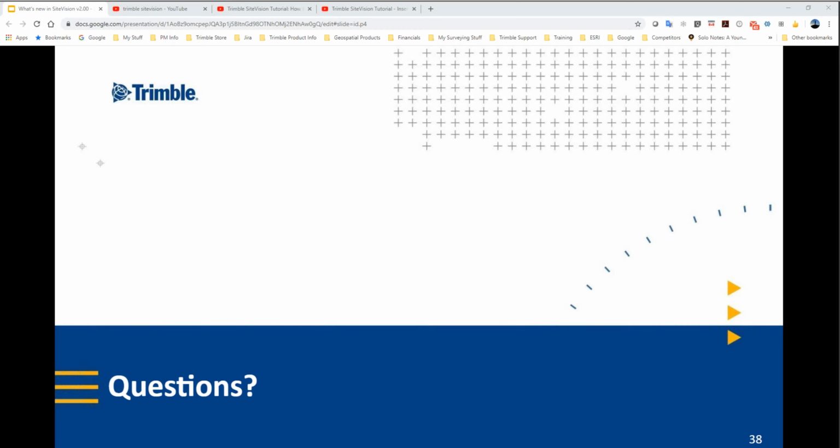And do you need to purchase TBC to use the AR exporter? That just came up, and I'll have to follow up on that one, because I've heard we have a viewer that's free, that you can use the AR exporter with that TBC free viewer. But my concern is that you don't have the ability to set a coordinate system with the free version of TBC. Without that, you're only going to get the scale only. So I'll follow up on that question. This just came up yesterday, and I haven't gotten the answer I was looking for yet.